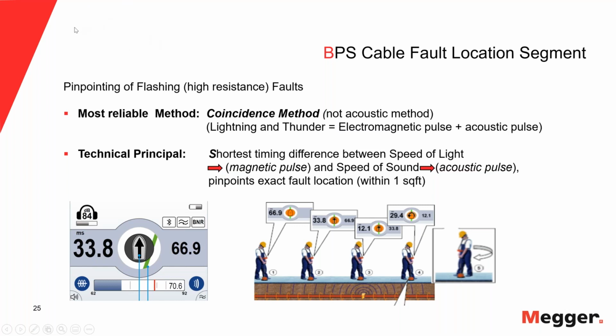And because, like Marshall was saying, typically I have to cut the cable, and I don't want to cut the wrong cable segment. So it's always good if you have a chance to verify a pre-location result with a pinpointing result. It's a very good practice, regardless of whether in conduit, not in conduit, or direct buried.